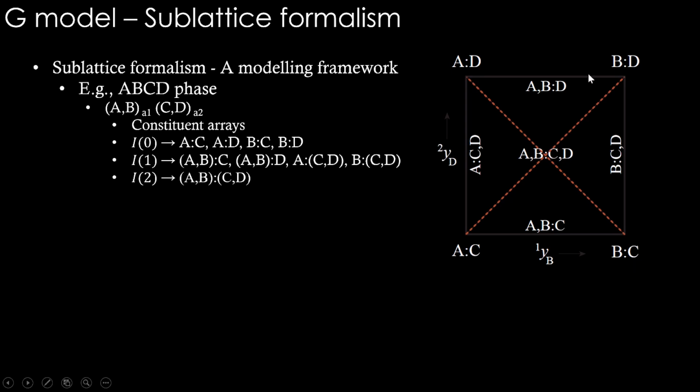Right? So, this is the composition space covered by this arrangement of constituent arrays. Now, what is important here is these corner values. The composition in these corners looks like a compound, like A and D joined together to form a compound, right? So these compounds are called end members, and the Gibbs energy corresponding to them will be multiplied by fewer mole fractions, because there are only two elements.